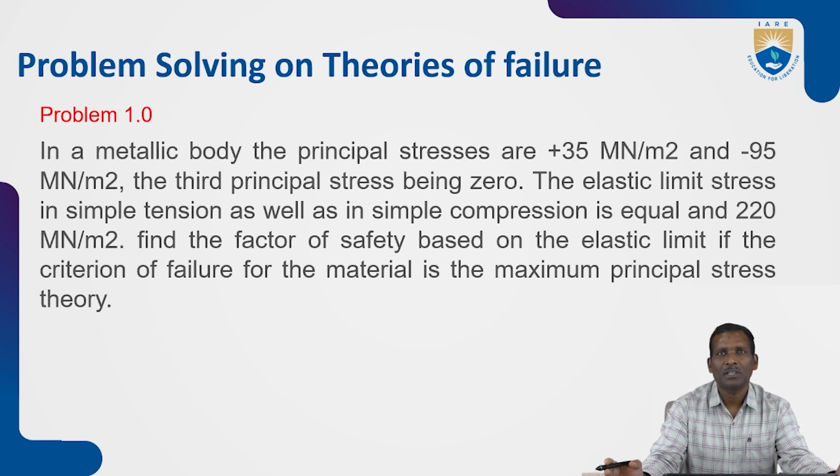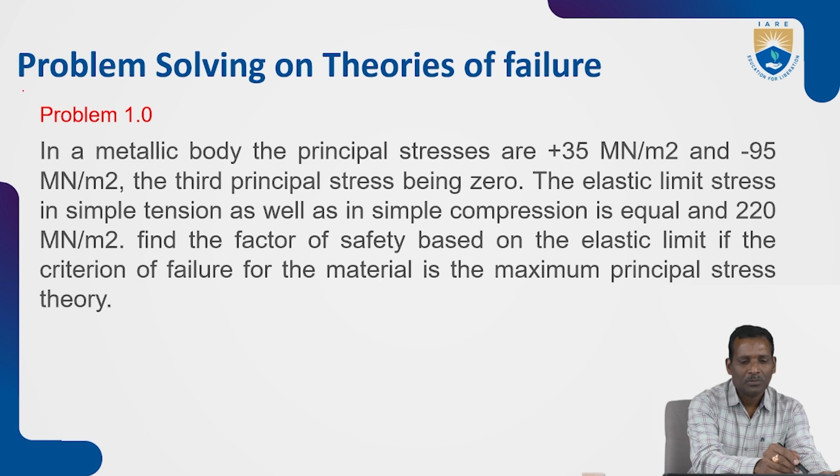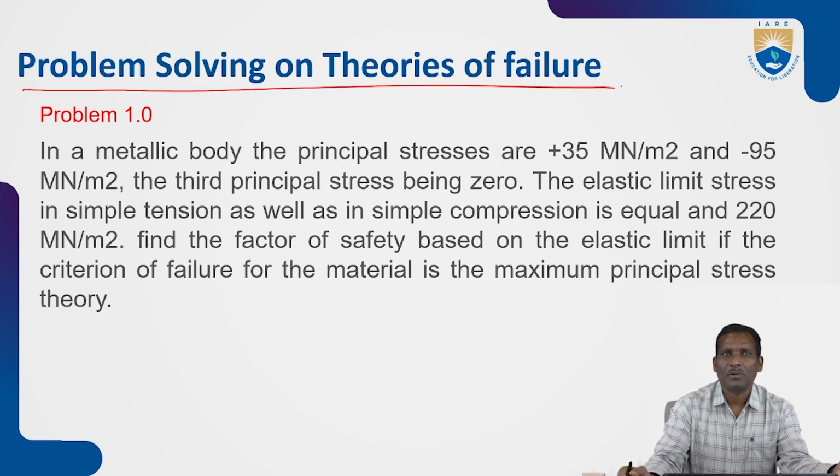You should use these theories of failures to avoid failure for safe design. Always for safe design, you have to use some theories of failure. So now in today's session, I want to discuss about the theories of failure related to the maximum principal stress theory and maximum principal strain theory. And later we will discuss about other theories also.